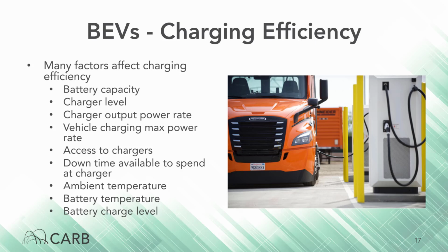The battery has to be cooled while it charges, and if temperatures are hot enough, some of the power from the charger is used to keep the battery cool rather than to charge it, and this will affect overall charge times. The same can be said for the inverse. In cold climates, some of the electricity is going to be used to warm the battery up.